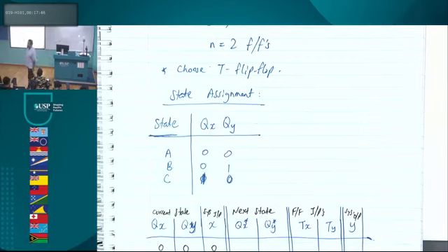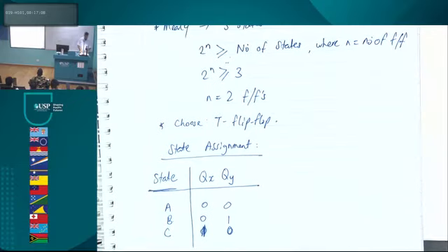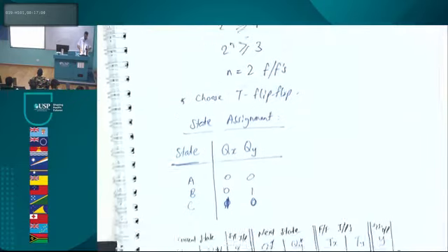Unused states can be catered for using don't cares. But only when we do sequence detectors. Problem 1 is a sequence generator, problem 2 in your project is a sequence detector, right? For sequence generators, we've got to point to an unused state. Otherwise, it'll go and get stuck in a corner, and it won't be able to come out of that corner in a sequence generator if by fluke something happens. In sequence detectors, you're not outputting a thing. So as your input goes in, it will self-correct itself, right? If you build your thing in software, you'll see what I'm trying to inform you of.